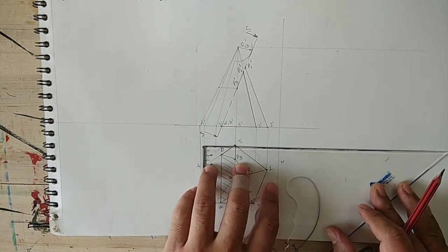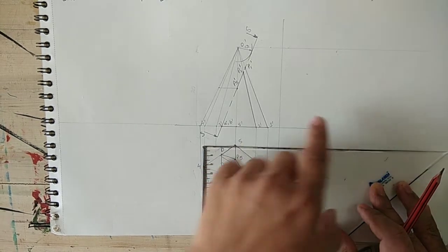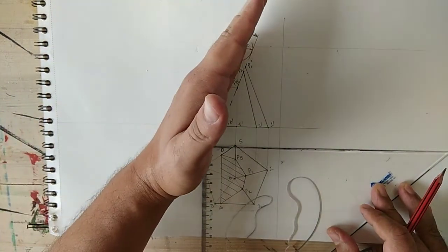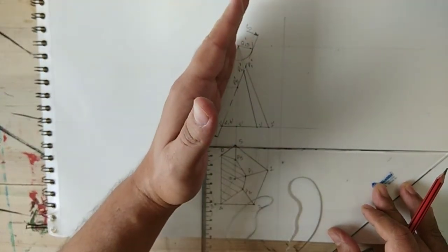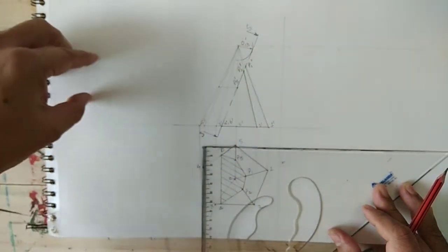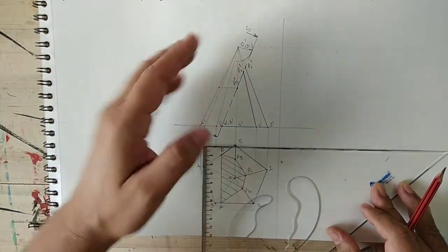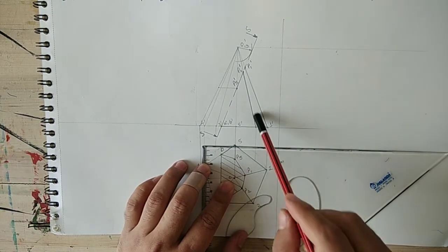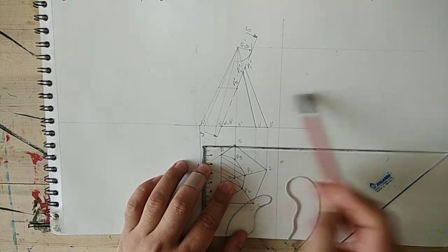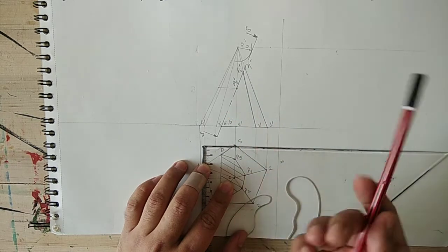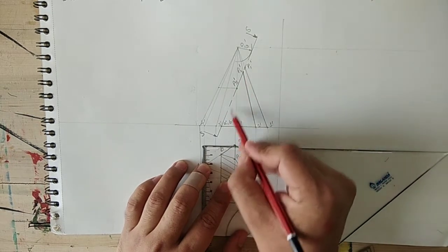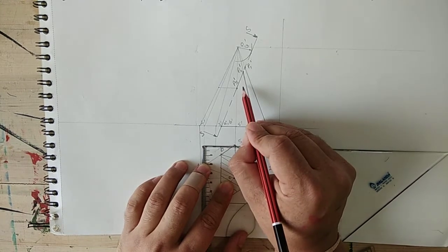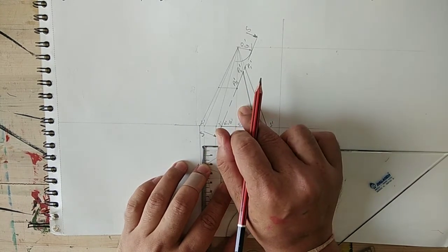The logic behind drawing this left hand side view is that the elevation of the sectional line is like this and we are seeing this object from this side. Suppose if students draw a right hand side view in this case, then we are not able to see this sectional area, so the right hand side view becomes wrong.